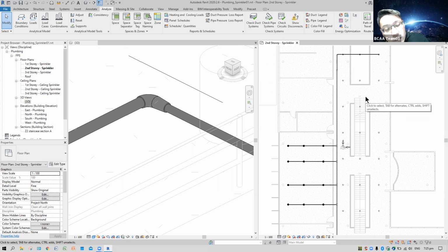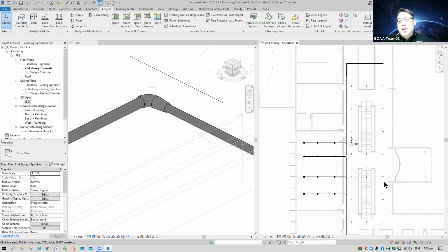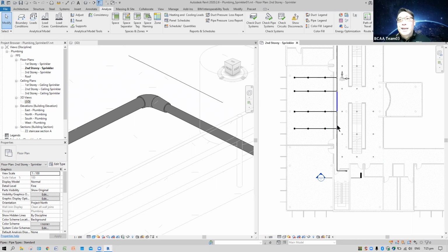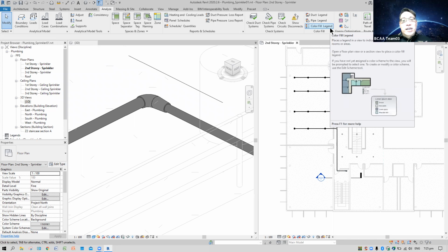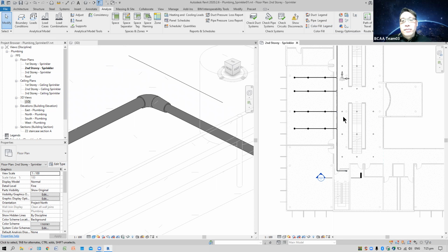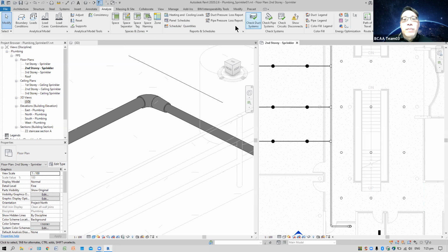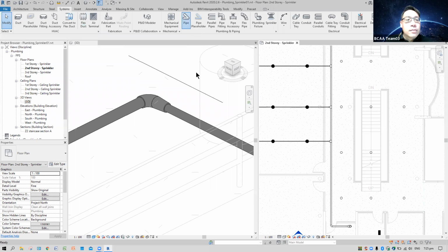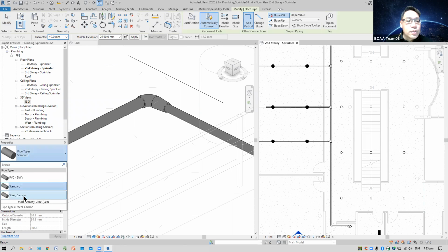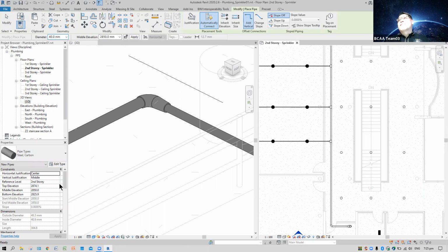Currently we're using the VPC. Just now you created the new scheme, I think. But we still need to reflect. So actually, by default, from the start, I should pick the one that I change. Now when I start to finish, I start to change too late already. So you can see now, if I go to add, draw my pipe, draw pipe system, you see, you can choose that carbon steel. That one doesn't have it.